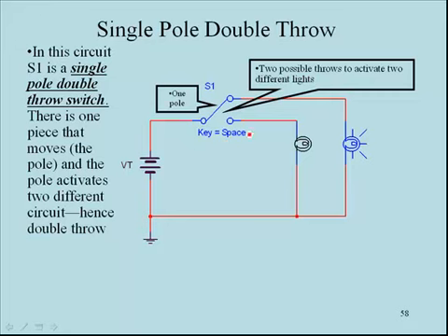Now again, this key equals space comes from Electronics Workbench simulation software. So what all this would mean is that if you were using this in Electronics Workbench and you press the space bar, it would change the position of this switch.